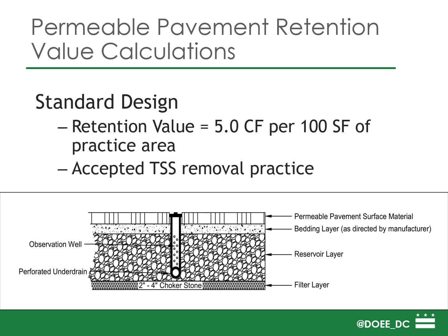It's also an accepted TSS removal practice, which means there is some sort of filtration mechanism occurring here. There's some settling and filtration happening to remove the solids in the runoff. In certain situations, you may need to achieve retention but also need some additional treatment. This often comes into play in vehicle access areas. Vehicular access areas must achieve a certain level of treatment, which I won't go into detail on. But if you need this additional treatment, you can look to practices such as permeable pavement that are accepted TSS removal practices.